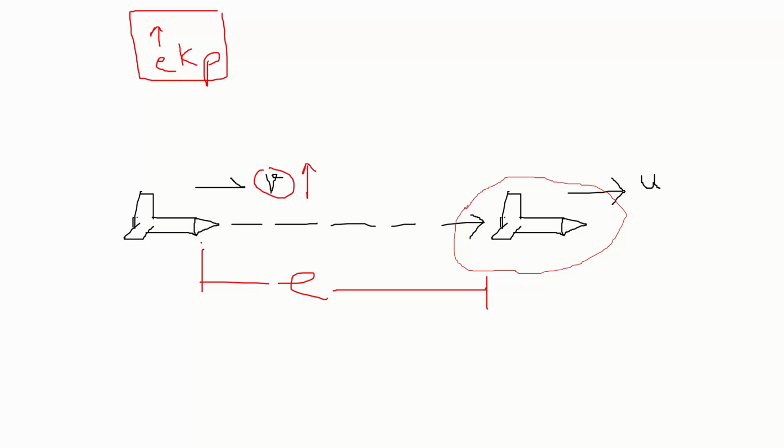And if this ABM attains the target very closely, and let's say it is moving with the same velocity as that of the targeted missile, in that case the error e will be small because they are very close to each other and moving with the same velocity. And moving with the same velocity means that the rate of change of error, d/dt of e, will also turn 0, which means the derivative block is going to give 0 as output. And if the error is very small, the output from the proportional controller will also not be considerable. So we can assume that to be 0 as well for small errors.